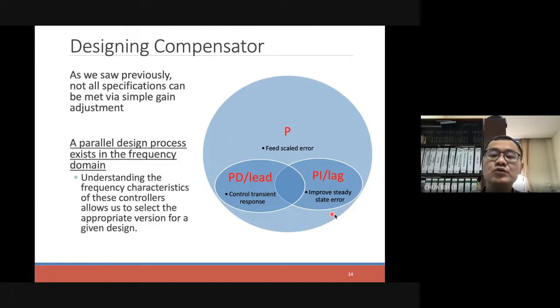So in order to improve the steady state error, we can somehow increase the system type. Yeah, increase the system type, then it becomes better and better, right? Okay, so that is the design technique or strategy. Okay, we increase the system type. Okay, then the steady state error will improve.